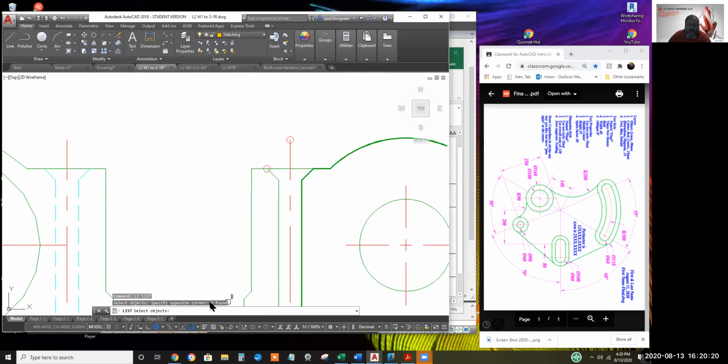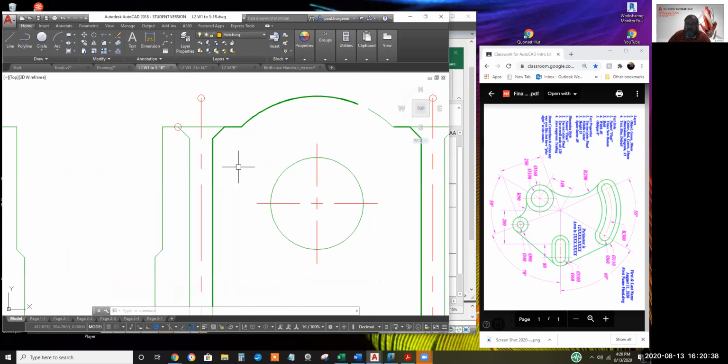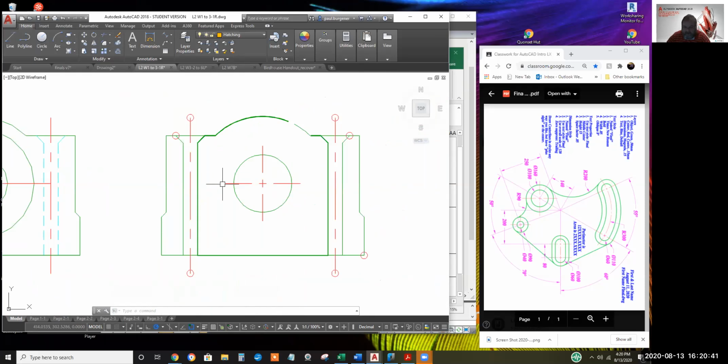Nothing has been found. So let's use one of the modify commands and use a regular window, and nothing was found. So that tells me it's a glitch with the display, like the octagons when you zoom in fast on a circle. I'm going to regen, and I think they'll disappear. So it doesn't answer what they are, but it gets rid of them. Okay, thank you. My pleasure.